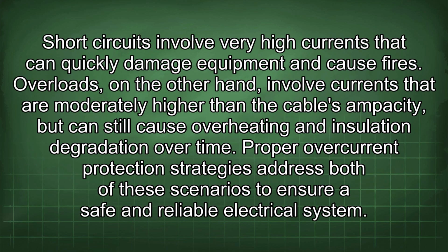Short circuits involve very high currents that can quickly damage equipment and cause fires. Overloads, on the other hand, involve currents that are moderately higher than the cable's ampacity but can still cause overheating and insulation degradation over time. Proper overcurrent protection strategies address both of these scenarios to ensure a safe and reliable electrical system.